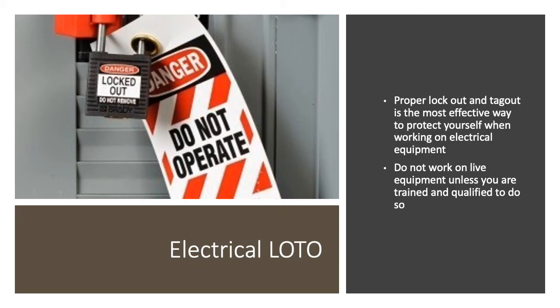So electrical lockout tagout is extremely important in these instances, just to make sure that when we're operating or maintaining equipment that it is properly locked out. So there's a lot more covered in our lockout tagout training, but most importantly, you do not want to be working on any sort of live equipment without it being locked out.